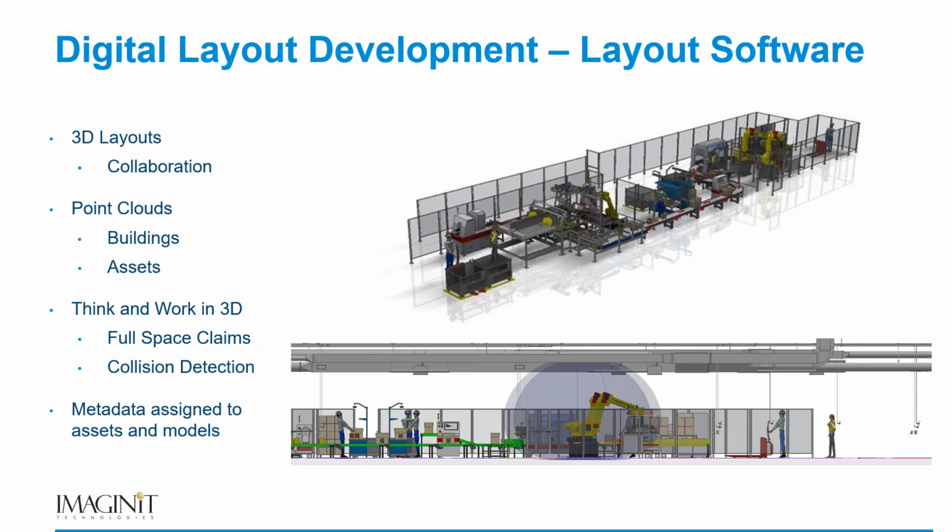So here you're starting to actually think and work in 3D with this full representation. In the lower right image here, we can see a robot arm that we put a sphere around to understand its total range of movement. And by having that in 3D, I can see really what's going to go on with how this thing's going to move and rotate. And if I need to tell the programmer to not go a certain height to risk hitting something, right? Or what happens if we do hit something? Maybe I should just actually move the HVAC line. So you can do a lot more with collision detection in a 3D space.